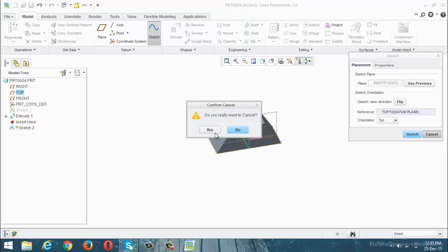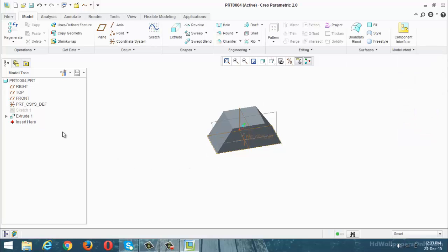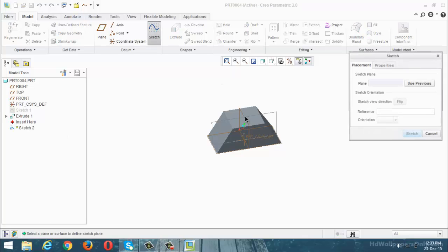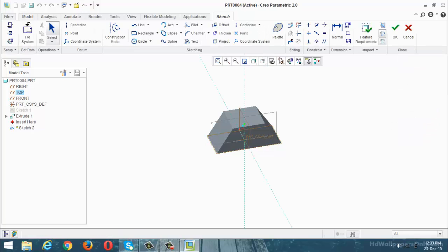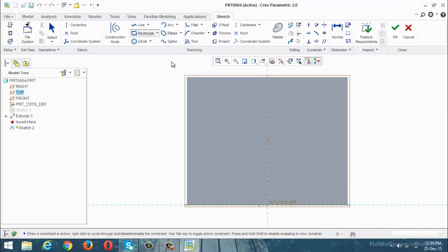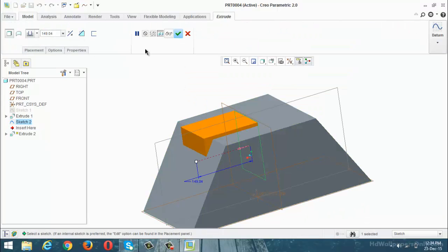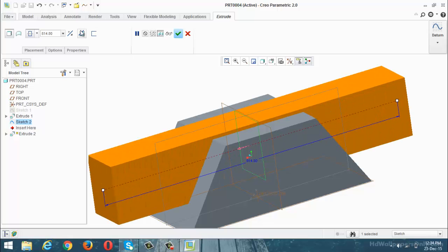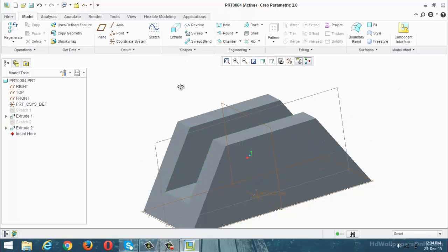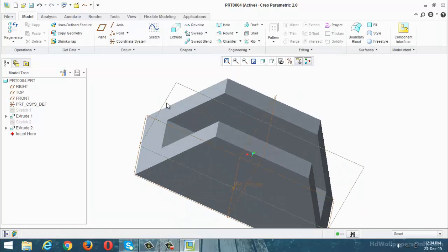Again, my requirement is with respect to this edge, the hole equal to some 30. For that purpose, you can design the datum plane, or otherwise a sketch. For through hole purpose, set to sketch view. Again, design in this format. Just apply the extrude. Place the symmetrical. Through hole means completely outside. Remove material. Okay. That is the process.